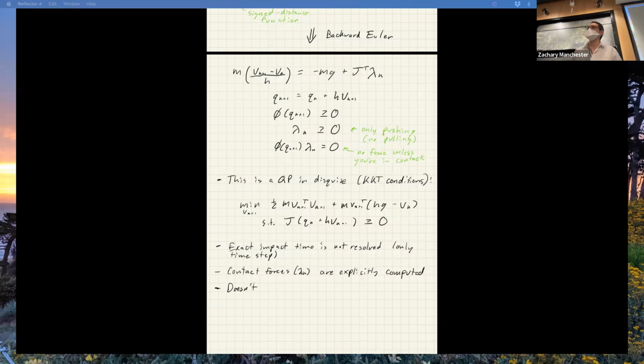This is often why if you ever use MuJoCo or Bullet, mostly Bullet does pretty much exactly this. So PyBullet, Dart, they all do this. You often have to take kilohertz or even a couple of kilohertz time steps in those simulators to have them not barf at you. And that's because of this. They're basically doing Euler. And as a result, the integration accuracy is not great and you need really tiny time steps.